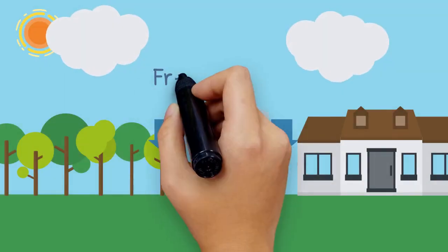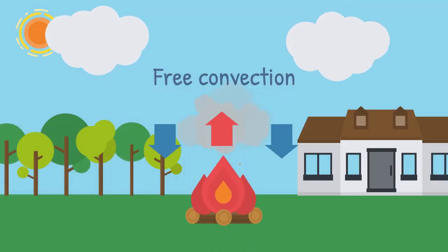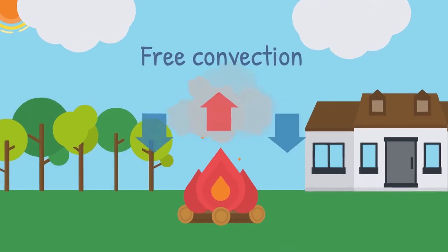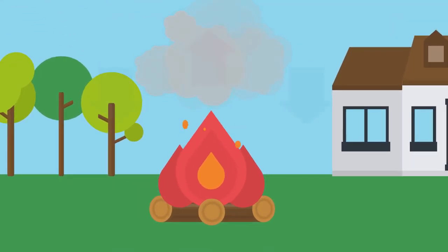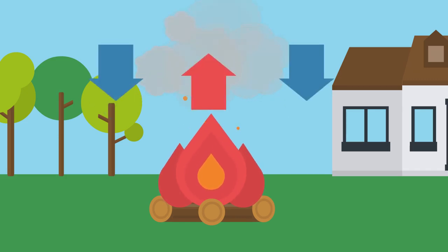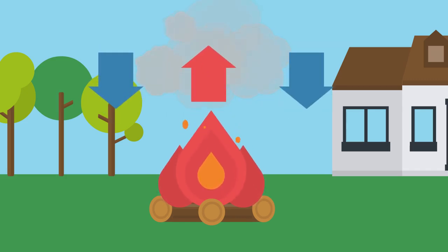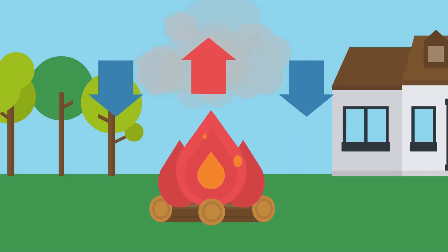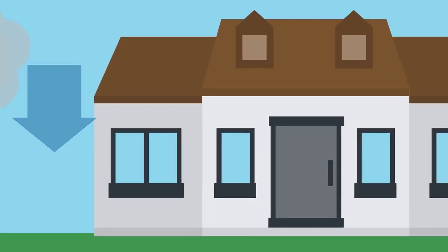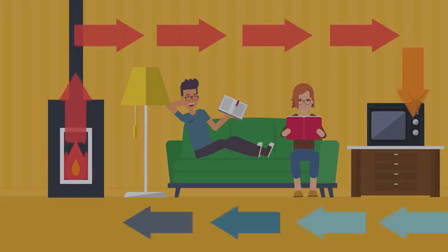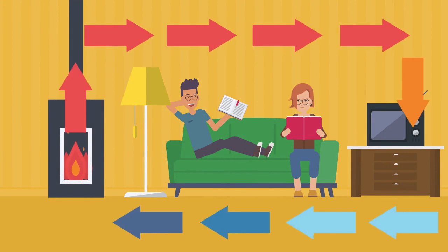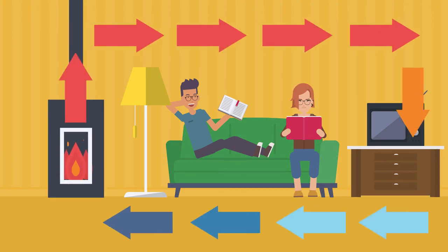Free convection is due to the recirculation of the fluid when there is no external force that drives it. In the campfire in the figure, the heated air decreases its density and, due to the effect of gravity and buoyancy forces, tends to rise. At home, the fluid surrounding a heat source becomes less dense and rises.